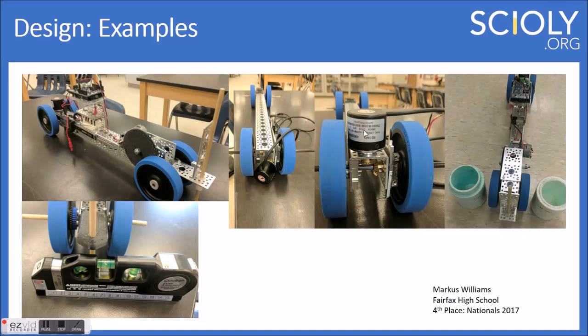Oh no, actually I believe this is the rear. Yeah, this is the rear. So the encoder to the rear with the bevel gears to allow that to read it. He had this DC motor here, just a simple brush motor with his large gear that he 3D printed. And I believe he did have problems with that gear, like little teeth on it snapped off. So I'd be very careful about 3D printing gears. Perhaps just print an extra spare one just in case something goes wrong.